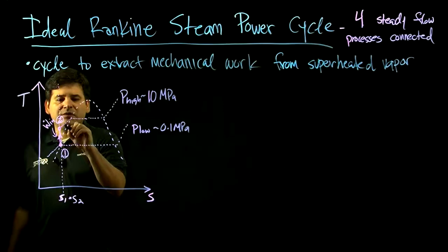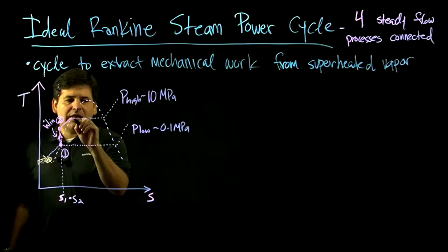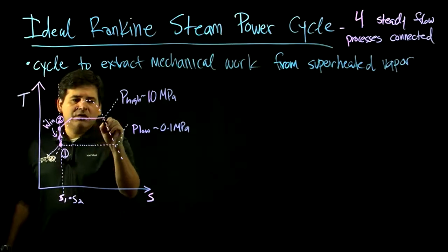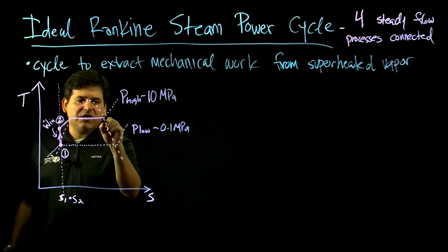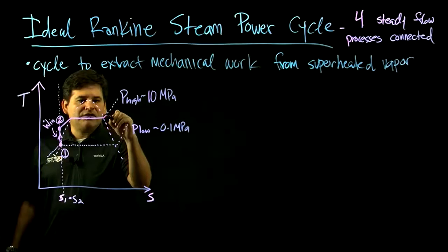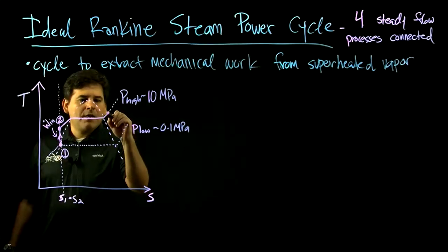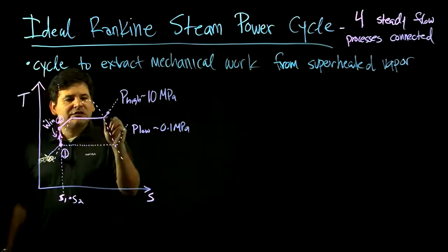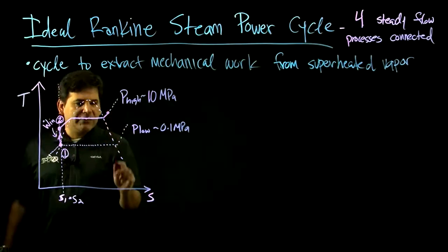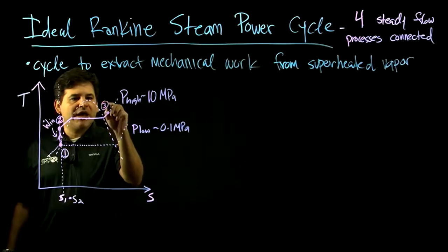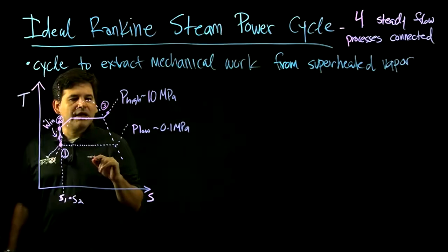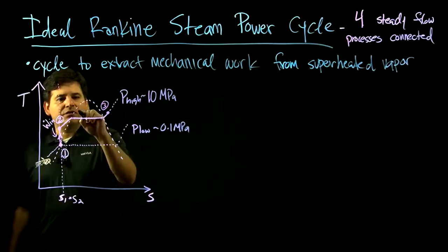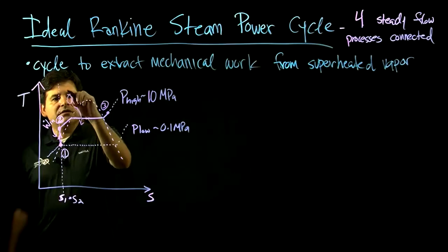The pressure stays the same, but the energy will increase, the entropy will increase, and that energy will keep on increasing until the temperature changes here, but it also undergoes phase change here where the temperature stays constant. Then you end up at this final state where the pressure is the same, but the temperature is increased, the entropy is increased, and you end up at state 3 in the superheated vapor region. The way that you get there is through heat transfer in.